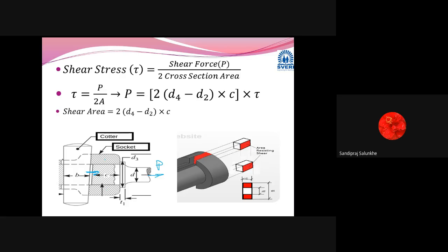Okay, spigot is inserted here. This socket is hollow, and this much area is the only area which is going to shear out if the shear stress exceeds its limit. Getting me? So we are going to calculate the shear stress tau. Now this tau value can be calculated from the material property, that S y t divided by 2 is the allowable shear stress.